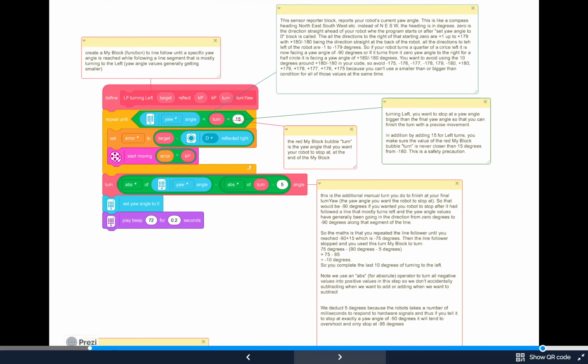Slide 11. This line follower that uses the gyro sensor is more difficult because you've got to follow a line while keeping an eye on the yaw angle inside your robot. If a course is snaking, we can use specific yaw angles as waypoints. You're essentially breaking the entire line-following task into direction change segments. Each time the robot completes a certain angle change, you reset the gyro sensor and treat the next segment as a fresh start.